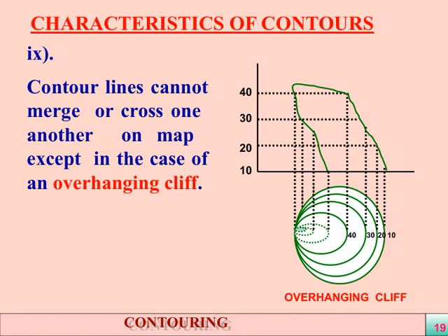So, whenever you're analyzing contours, always check for these closed-loop patterns to confirm the data's consistency and correctness. Now, let's talk about contour lines and their behavior on maps. One key point to remember is that contour lines cannot cross or merge with each other under normal circumstances. This is important because it helps us understand the terrain without confusion.